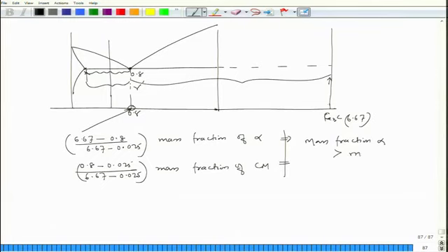Now, to find the alpha in pearlite, it would be decided by (6.67 minus 0.8) divided by (6.67 minus 0.025). This is the whole mass fraction of alpha, and the cementite mass fraction would be the remainder.